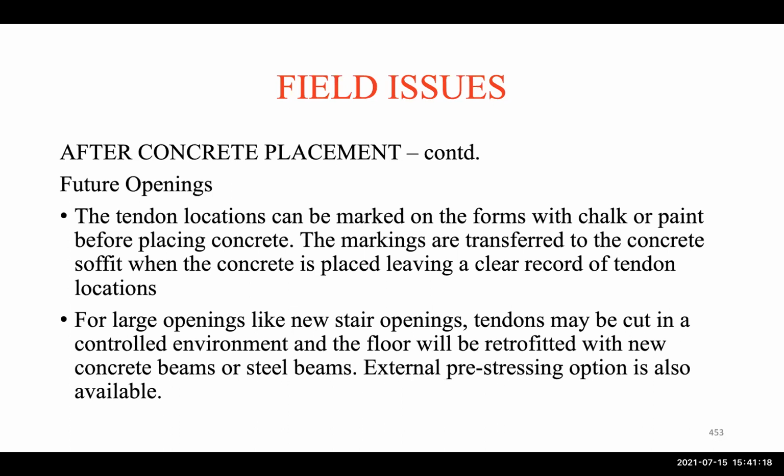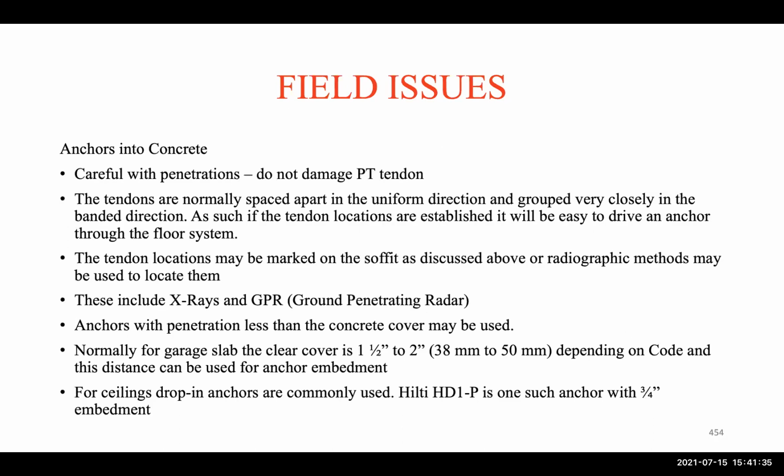Okay, and these days, with the increased use of PT, usually the engineers provide the layout of the tendons, so mistakes will not happen in the case of, for example, drilling something, having a future opening, or even hanging things from the slab.